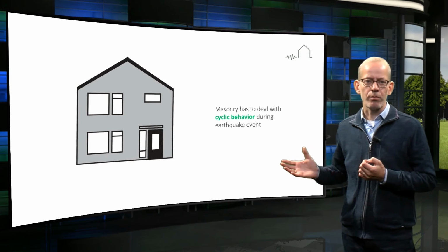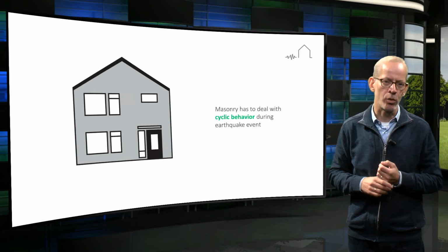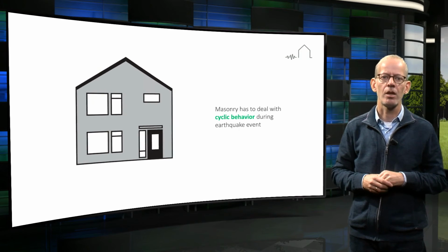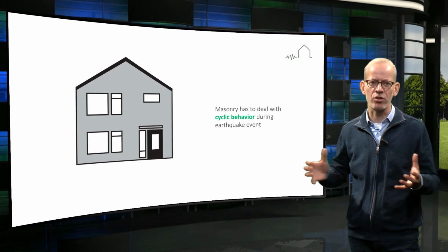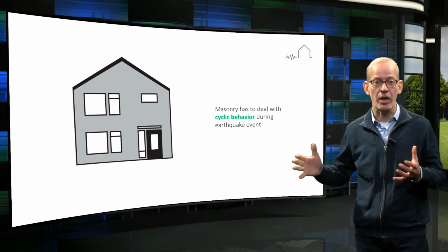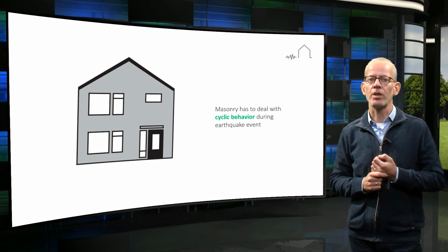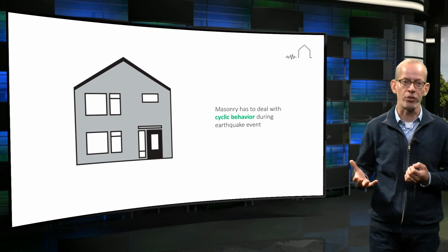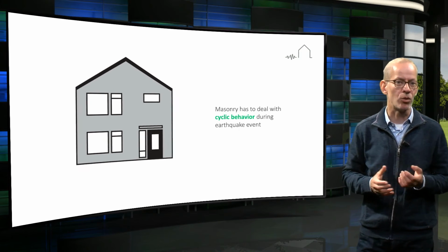In the material diagram from these examples, a gradual increase in loading is assumed, going stepwise from a small load to failure load in compression. And this brings us to a further complication. A house that is accelerating due to an earthquake will not deform only once, but back and forth, sometimes even during several seconds or minutes. Determining and predicting this cyclic behavior of masonry adds another difficulty. We need laboratory tests and computer models with cyclic loading.